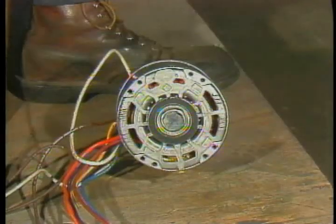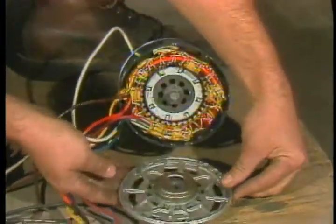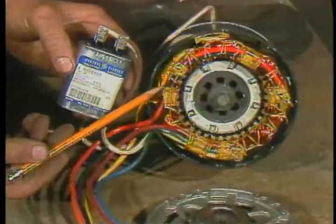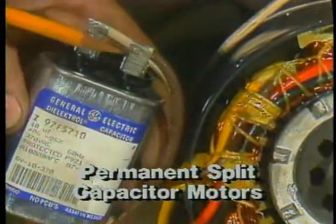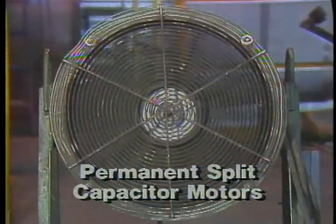There is no centrifugal switch in some motors. The start windings are permanently connected in series with a continuous duty oil-filled capacitor. These are called permanent split capacitor, or PSC motors. Their starting torque is much lower than capacitor start motors, but they are very simple and run smoothly and quietly.